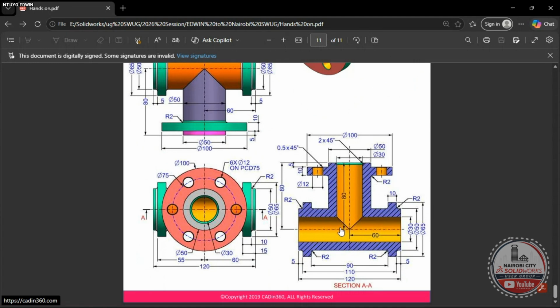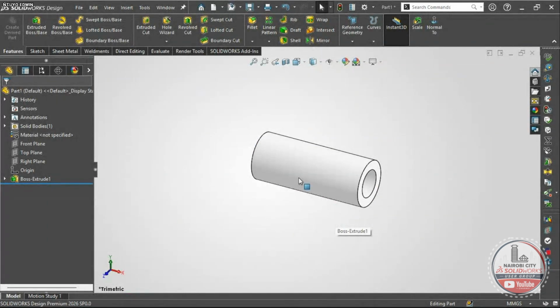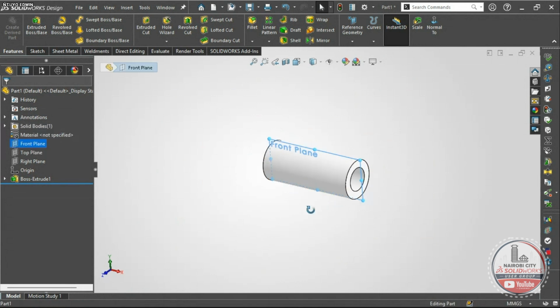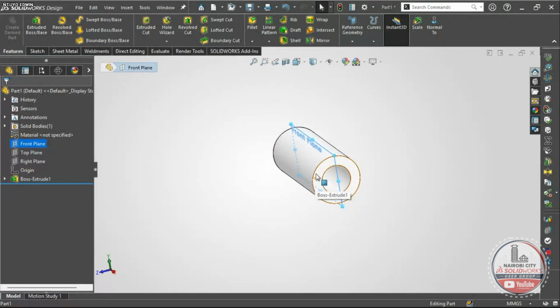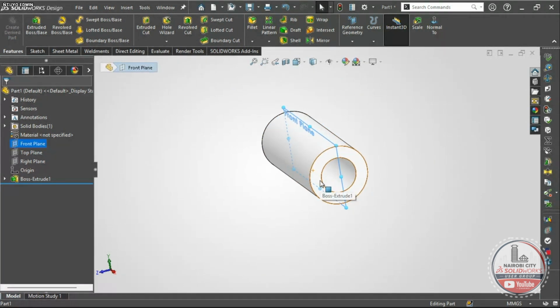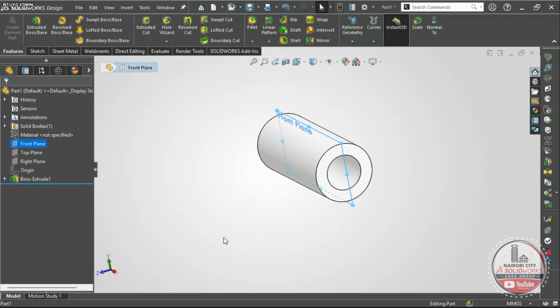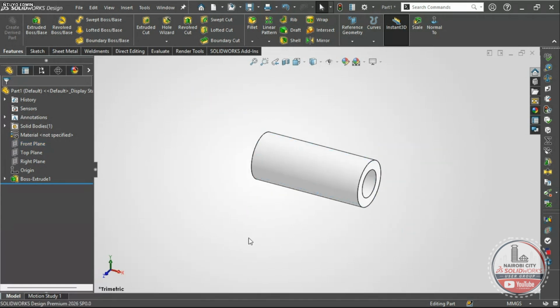So what we are going to do for this case is introduce something simple called a reference plane. We need to offset a plane that we are going to draw onto, because the moment I use the front plane, draw onto it and then extrude boss, it can work in two ways. The first way, I can offset the sketch to start from this surface, or I can just extrude and then delete the inner surfaces. However, that will be more hectic in my point of view.